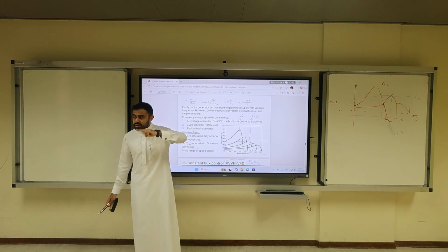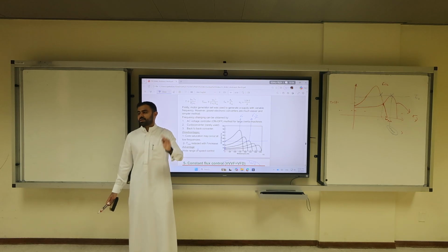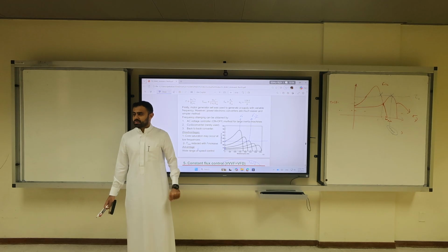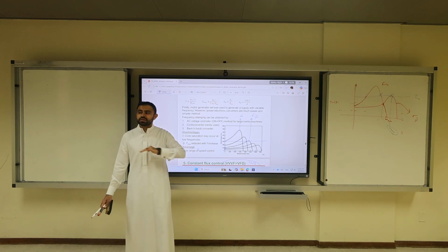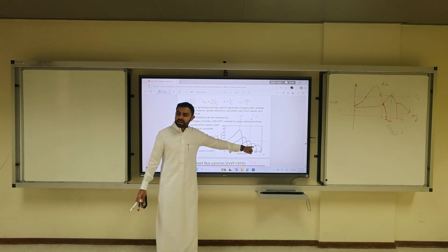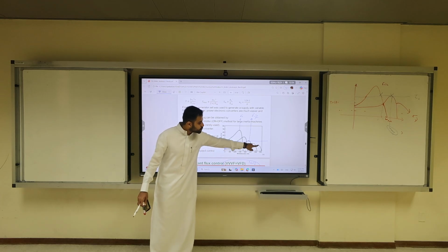So the machine would start spinning, and there will be inertia. Now this is in theory. In real life, you have to run at starting torque, because you're going to have so much high current until you drive the machine. You don't want to wait until the max. But this is from the machine's perspective, not the shaft perspective. You understand what I'm saying? Is it clear? Yes. So these two curves will not drive the load.